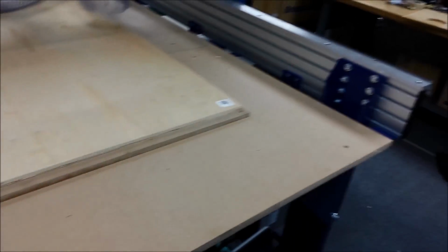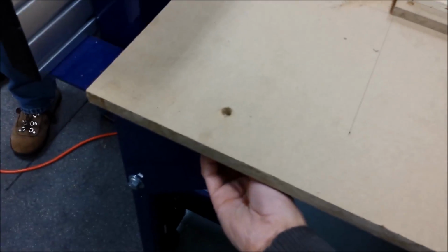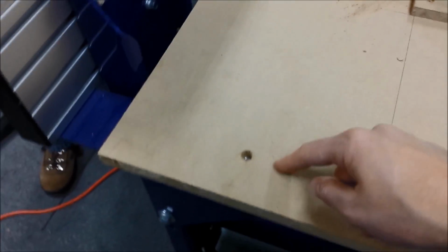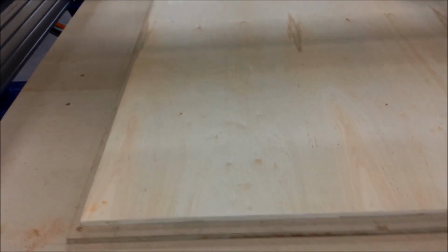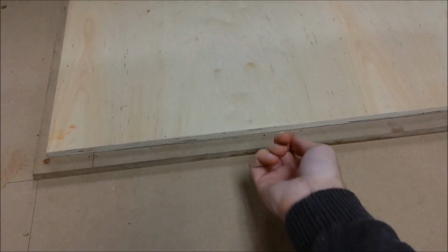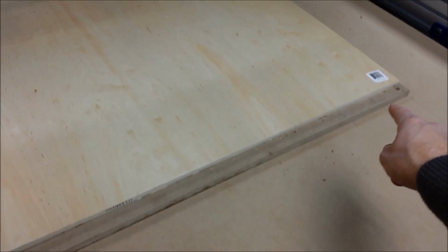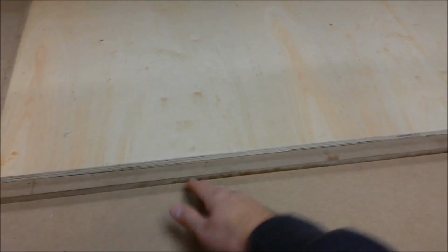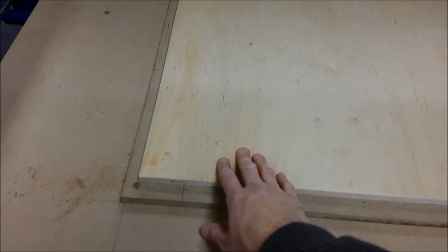So this is the way we've set up the ShopBot here. We have several cut sheets of 3/4 inch MDF that is bolted to each spanner, and we put insets in here and bolts through the bottom. And that's really cool because we can adjust the height of each of these from the top based on the inset. And then the cutting area is like 10 foot by 5 foot, and we have this sacrificial piece here of, we were going to do 3/4 inch, but they sold out of it, so we got 1/2 inch MDF, and we've tacked it down in the corners. And this is actually 1 inch bigger on either side from being a 4x8 sheet, and that works pretty well because that gives us the ability to put our stock on top and have a 1/2 inch hang off on every edge.